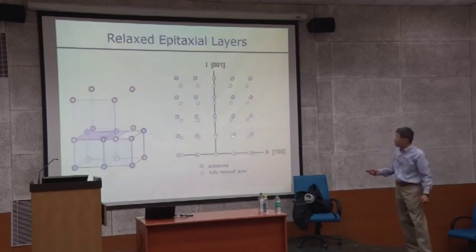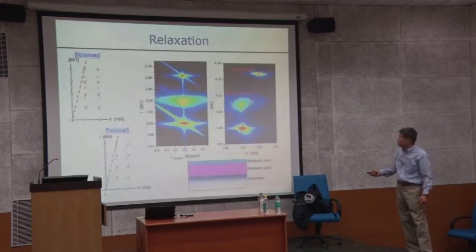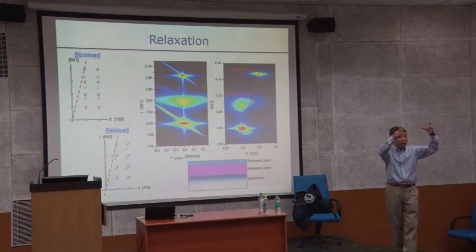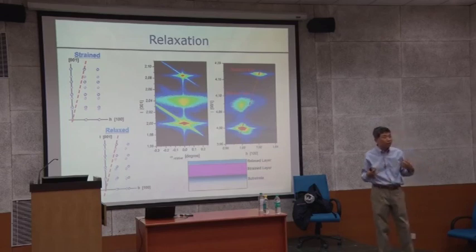In this case, look at that, the thin film on top of this is a relaxed one, going to a smaller value of H. But this value has a larger value of H. And then this separation gets bigger. So from this, I can tell right away that the material growing on top has a smaller lattice parameter and smaller volume than your substrate material. Understand that? Is it too complicated?